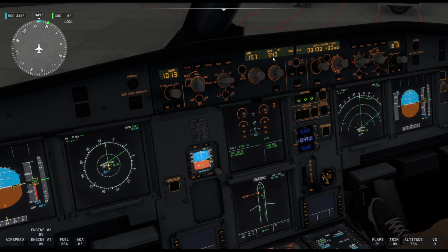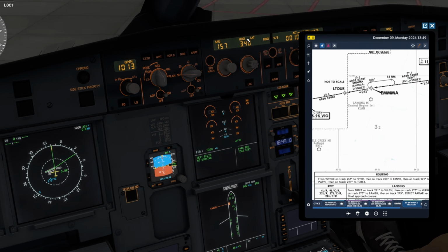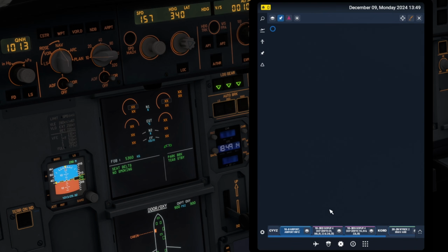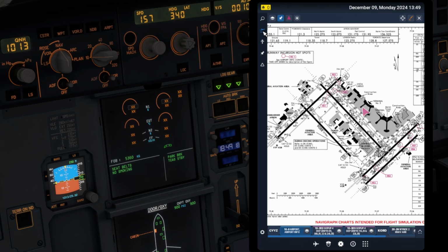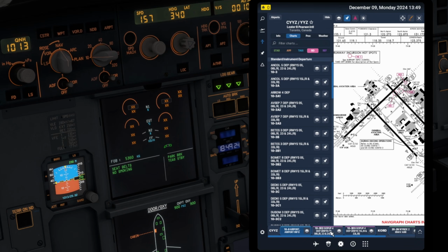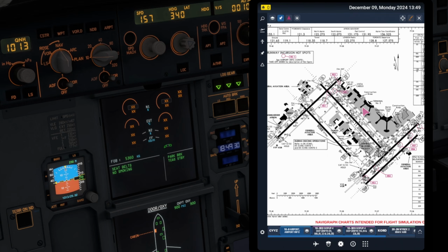And then we need the runway heading for this. So let's open our charts again. We'll be using the MOTS. And let's go to our 10.9. That's our airport info chart. Again, this will be available through the normal menu. You can click on the airport, whether in your flight plan, click on that, or search the airport. This is just easy because you can pin charts yourself, but Navigraph is very smart and it typically pins the ones that you need.